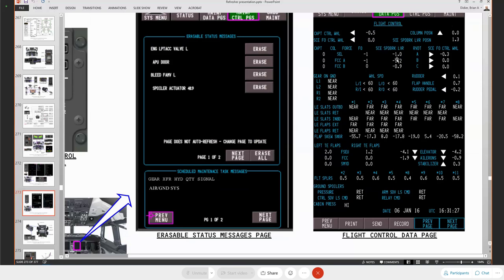your speed brake lever transducer. Okay, remember on the speed brake lever we have a transducer, channel A, channel B, and channel C. This information, this right here should be an average of this information. And then your control wheel is from your transducer on the first officer's control wheel. Okay, and you have 3 channels there also. 3 channels are there for redundancy.